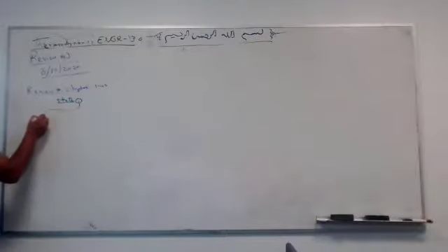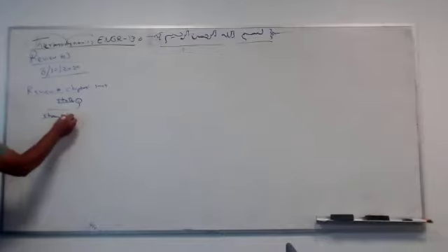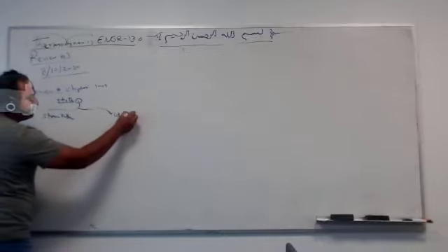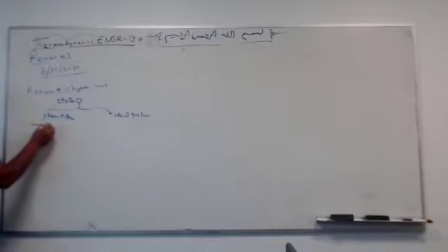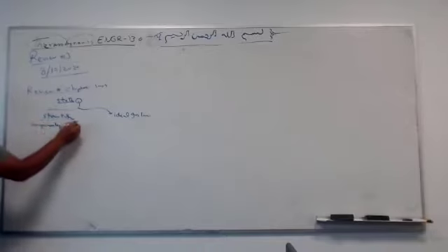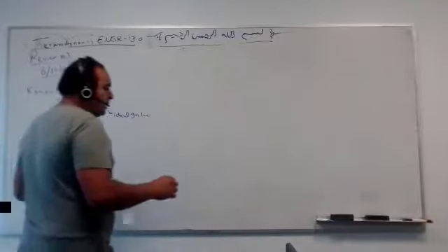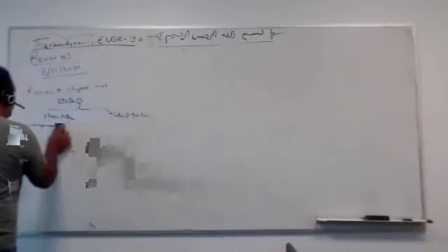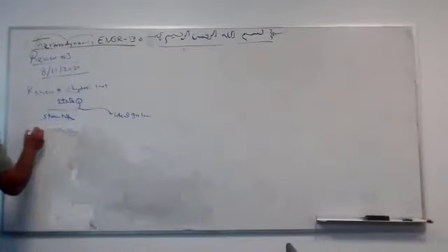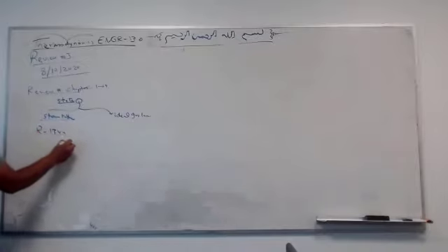You have either a steam table or the ideal gas law. For a steam table, it depends on the state. It can be compressed liquid, like in a compressor or pump, liquid. You have saturated mixture. You have superheated vapor. This is the steam table. So you need to know how to access the table: table A4, A5, and A6 or A7 for water. For refrigerant 134A, we have table A11 through A13.